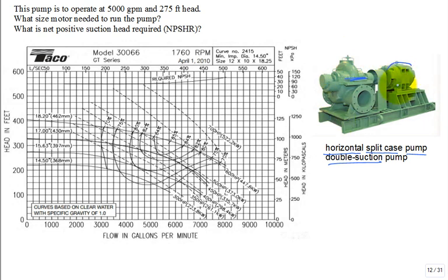There's a big motor here on a skid. The skid is to keep everything aligned. That's great if they align it at the factory. If you have a motor hooked up to a pump and you have misalignment, it can eat up bearings so fast. So you get it on a skid, you just pallet it in, put it down, and hook it up.